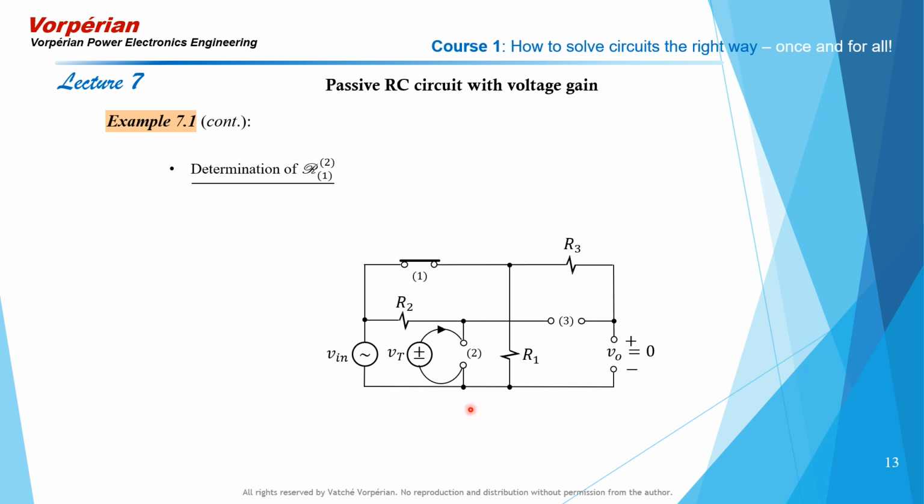We now determine the null resistance looking into port 2 with port 1 in its opposite state and the response nulled. The reference state of port 1 is a short, so when you are determining script R21 in this case, you have to open port 1.